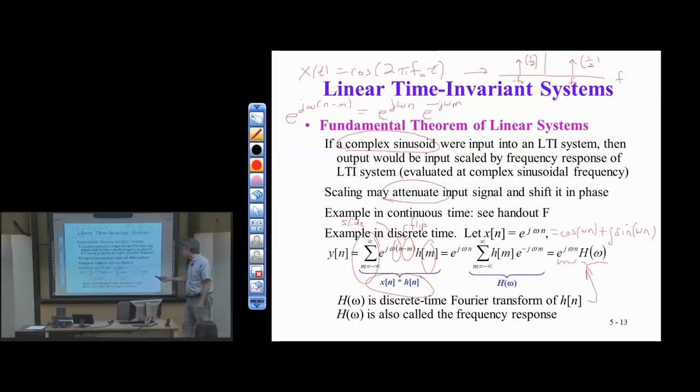Okay, so this is the frequency response of the LTI system. And it is true, it may not exist. There are some weird cases where we don't have one. But we certainly have one for bounded input, bounded output stable systems, because we can convert the Z transform into the Fourier domain. So again, back to the statement at the very beginning.